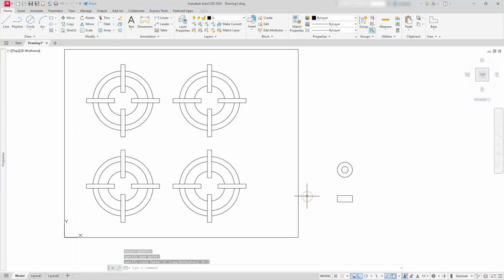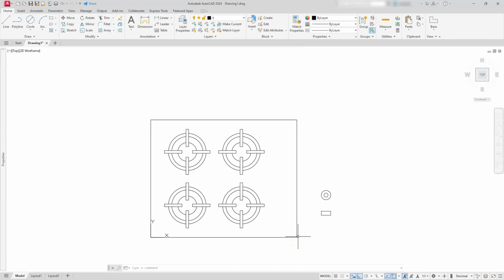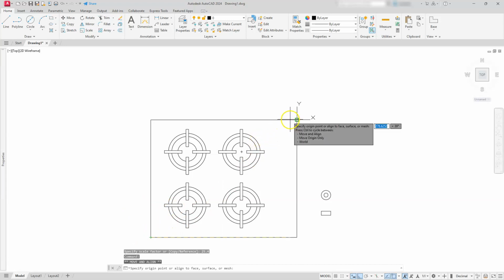Okay, so let's go ahead and place the knobs now, right? So our distance for our knobs happen to be along this point here. So it's actually, what, 23.4 going backwards this way, and then it's 40 coming down. So the ideal location to move my UCS is by selecting here, and then I'm just going to place it at this top end point.